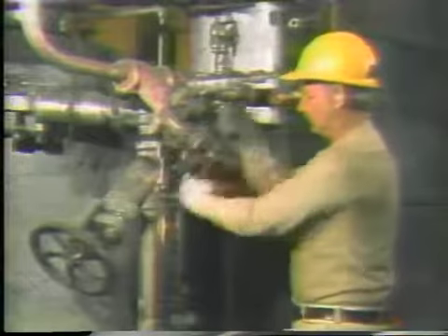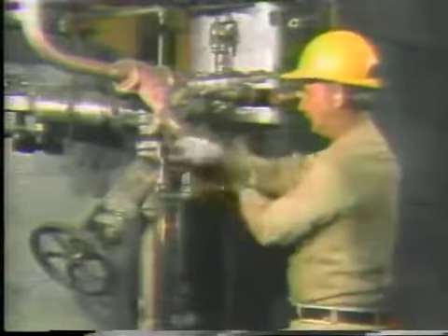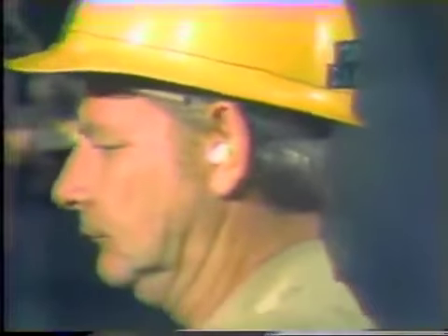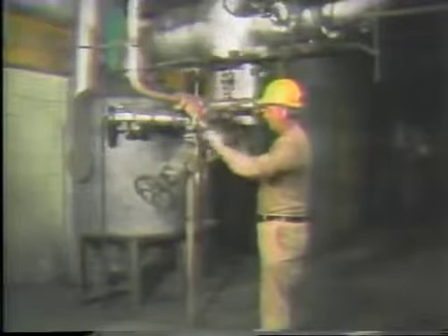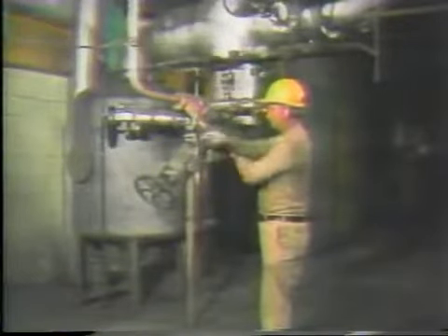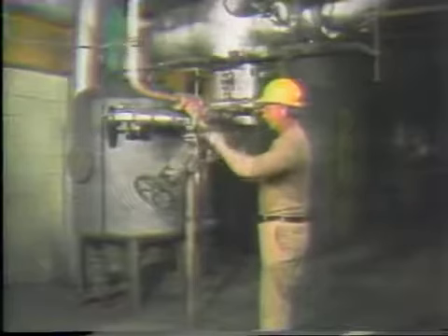A power plant is full of machinery that generates heat and steam and makes noise. To protect yourself from hearing loss, it's a good idea to wear approved ear protection in noisy areas. To protect yourself from heat and steam, you can wear a long-sleeve shirt and cotton gloves. Burned shirts and gloves are easily replaced. Burned tissue and skin takes a lot longer. Remember, you won't feel superheated steam or hot water until it's too late. So protect yourself. It makes good sense.